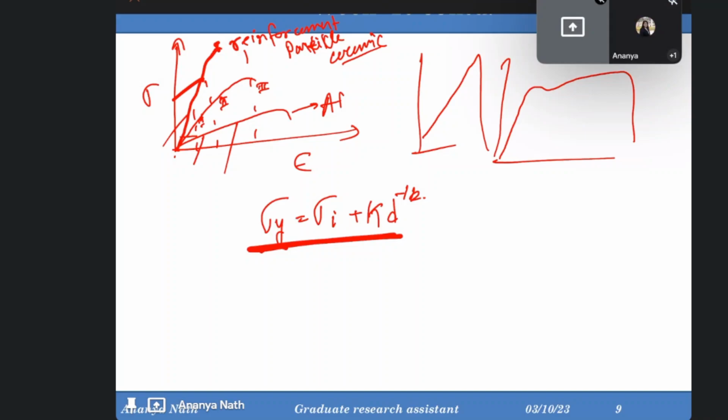Yes. It was shown, like if the grain size is 16, in some of the papers. I got some of the papers from some NIT people. What they have done is they have mixed Al2O3 as a ceramic nanoparticle in aluminum alloy, and they said that if the grain size is more, like 12 to 16, they have a surface for other grains to nucleate over it. Yes. So then strength will increase. They said that it is PSN, particle stimulated nucleation.